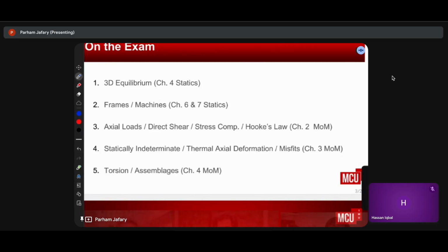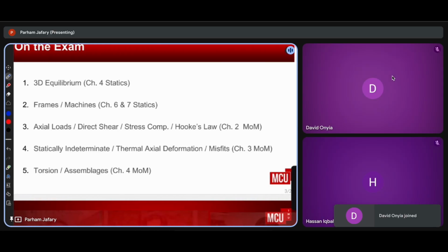Free body diagram, yeah. So the first step of every statics and mechanics of material question is drawing the free body diagram, and if you draw it correctly, you'll most likely get an idea on how to actually start and solve the problem. So I have already drawn the free body diagram here. For drawing the free body diagram, you remove all the supports and you replace them with forces or moments, if applicable, okay?